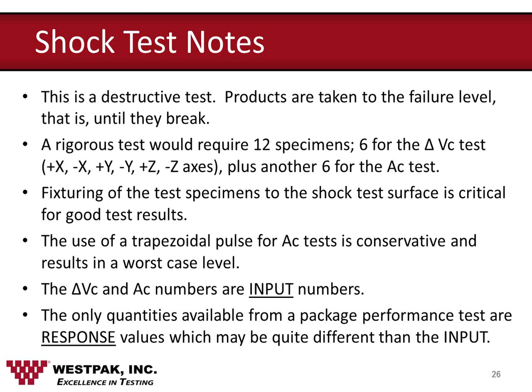That is, one for each flat face of the product, top, bottom, left and right, front and back, and then one for velocity and one for acceleration testing for each orientation. The test results are highly dependent on good fixturing of the products during the shock input. This can be tedious and expensive at times, but it's often well worth it.